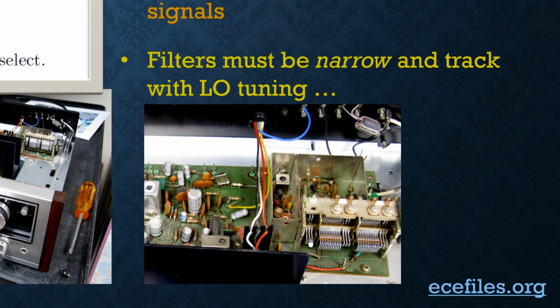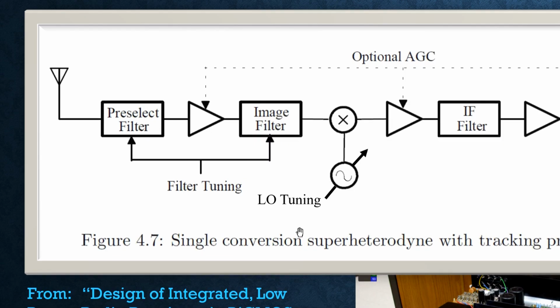And it looks like there's, let's see, 1, 2, 3, 4, 5. Well, okay, so these big ones are for the AM broadcast band, but these smaller ones here, here, and here are for the FM band. One for each filter and one for the local oscillator that's used in tuning. And they vary together, of course.